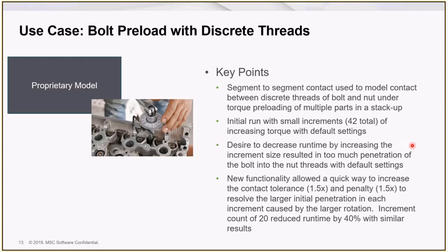I won't say that's a regular occurrence, but just keep in mind that it is possible, that not every time increasing increment size directly translates into a faster analysis. In fact, pretty much every analysis will have some point at which going to larger increments does not necessarily result in a faster analysis.